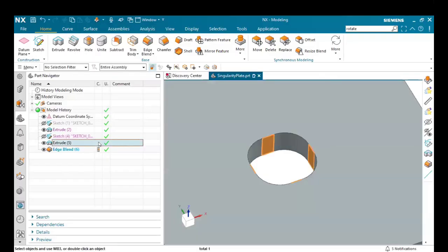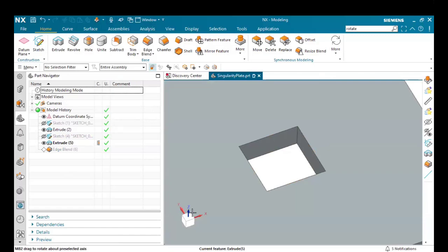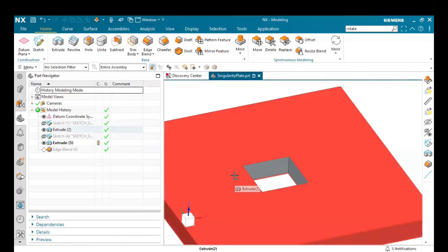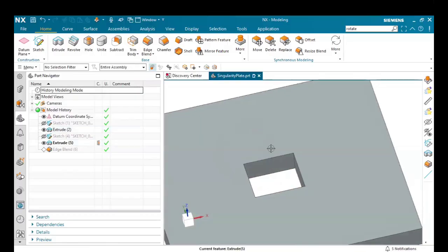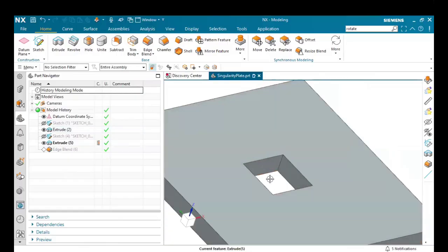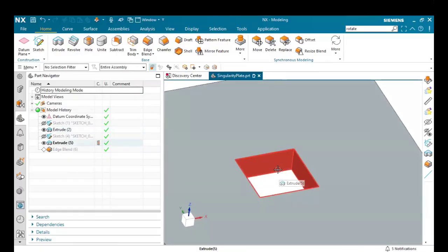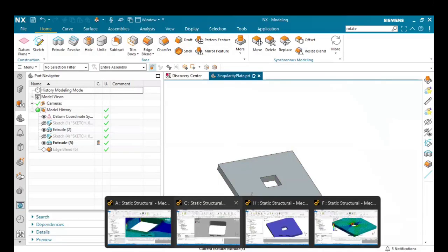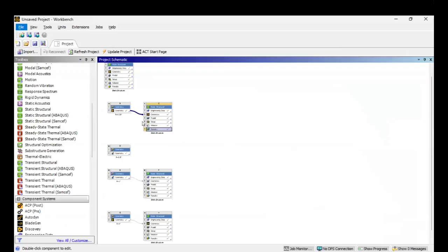For this class example, I'm going to show you how you can refine your mesh and how you can hopefully detect if you have a stress concentration. So I'm going to be loading up this plate in ANSYS. I think this should be easy to CAD if any of you are following along here. It's just a 12 by 12 plate with a 2.5 inch square in the center. I'm going to load it up in ANSYS. I've CAD'd it up already, so I'll just open the ANSYS file.